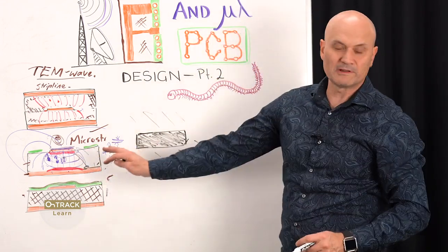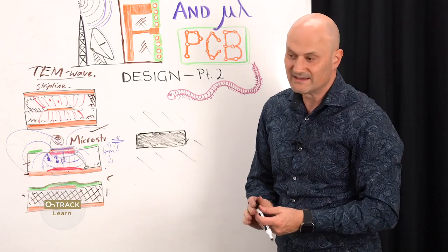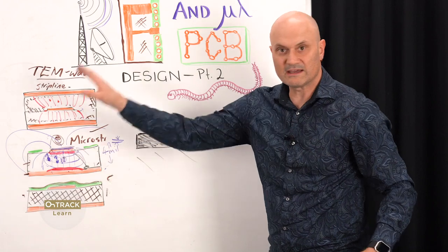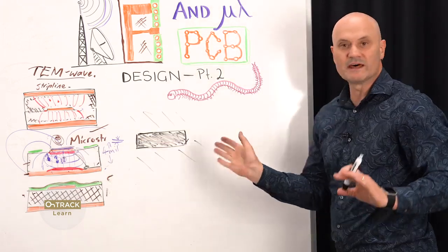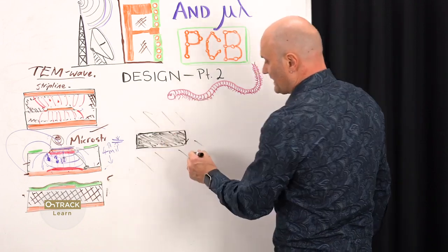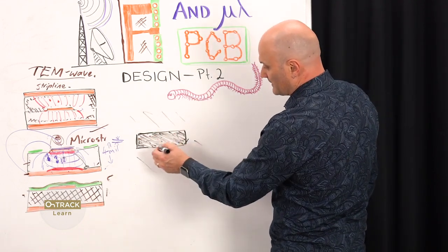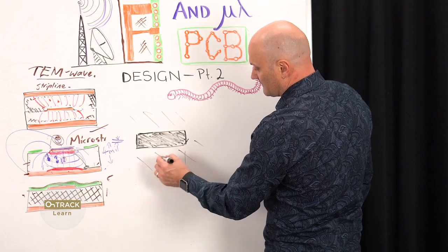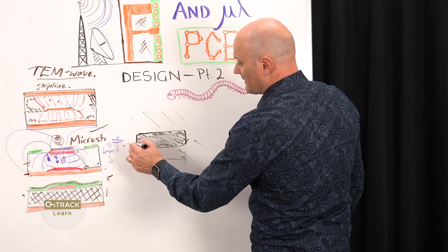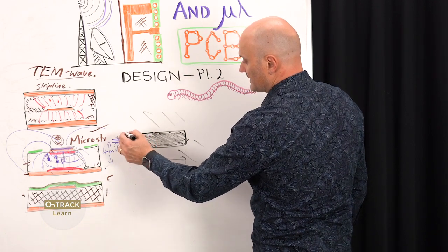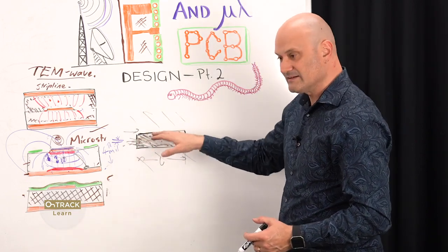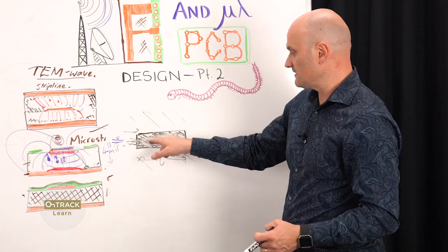The only time your copper plane is removed is when you want an antenna and you're intentionally causing these fields to radiate out. And that's another episode towards the end of this series. So we're looking down on top, and we may have a chunk of copper like this, that maybe it's a certain length, L, and somewhere up here we have a pin of an IC which is transmitting, it's a source, it's sending data in the form of RF energy into this trace.